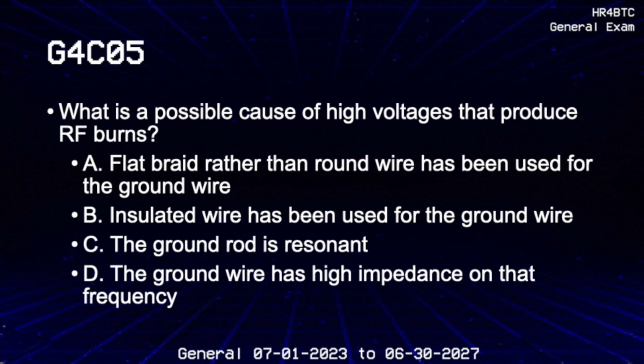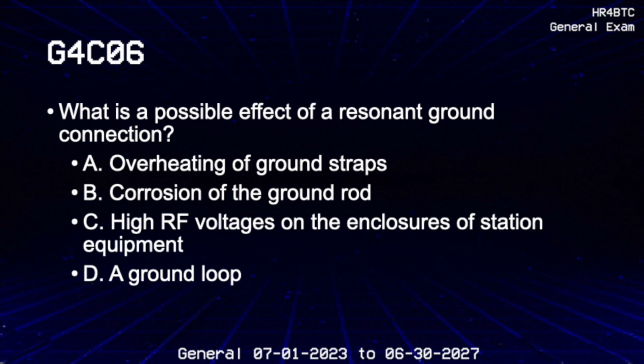What is a possible cause of high voltages that produce RF burns? The ground wire has high impedance on that frequency. What is a possible effect of a resonant ground connection? High RF voltages on the enclosures of station equipment.